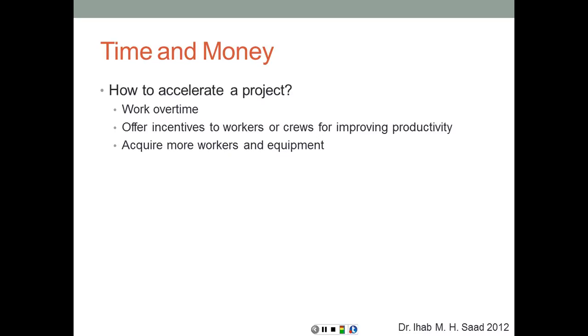Other options, which is unfortunately what comes first to some people's mind: work overtime. Overtime might not always be the solution. Or offer incentives to workers or crews for improving productivity. Within the same time, if you can finish more work, you're going to get a bonus. Or acquire more workers and equipment, again, to work within the same time so that you don't have to work overtime. Because overtime, by the way, you know that you're going to pay a premium for it, maybe 1.5 times the average rate, while you're not getting the same productivity.